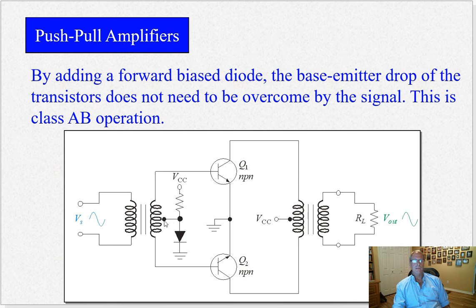And we put a center tap in this transformer to bias it up by 1 diode, okay? So this lifts up this point to 1 diode, which makes these transistors almost turn on. They're just sitting now ready to rock and roll, so that even the slightest little voltage that comes in on the input causes them to conduct.